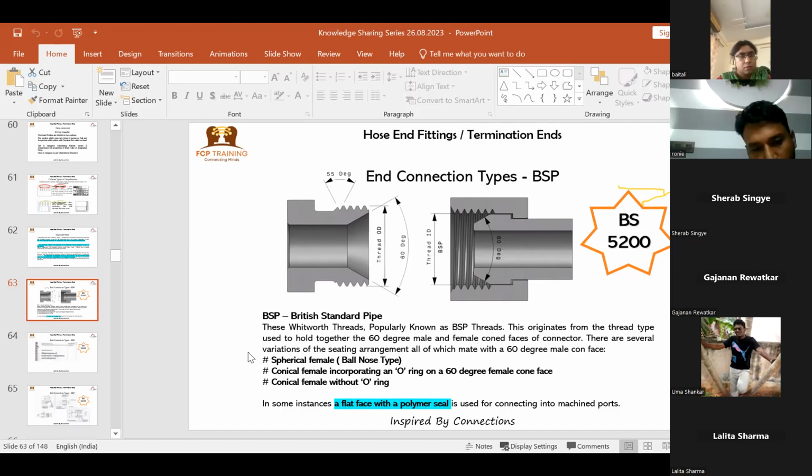Then when Boeing came into the picture, Boeing and even Parker Meggitt changed the fitting level to some different standard, some metric and some in JIC. They kept it in JIC, and every industry has its own standard. Even though they are aerospace standards, the dimensions change. Again, the material is not carbon steel or stainless steel, it is sometimes titanium and so on. The alloy comes into the picture there.